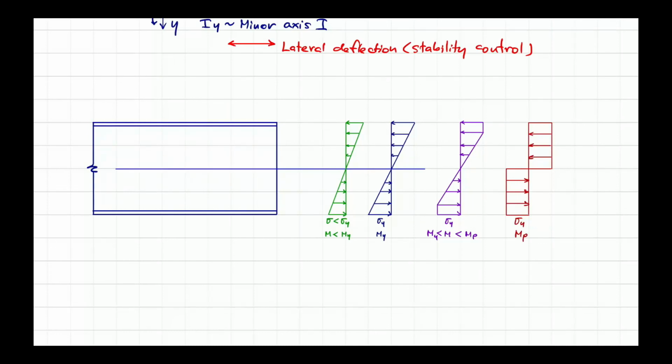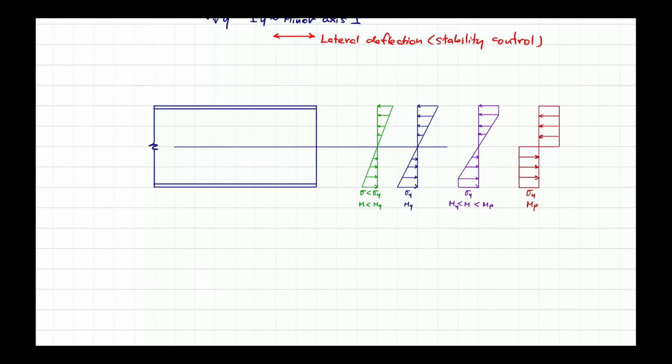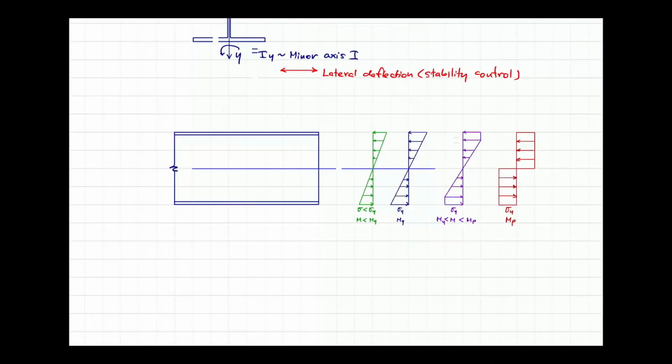So you apply a large enough curvature that makes your strain hit the yielding from pretty much from here, but in reality your beam will not undergo that large deformation, to be able to mobilize the sigma y at both corners. If you look into the moment curvature response, this is what you get.